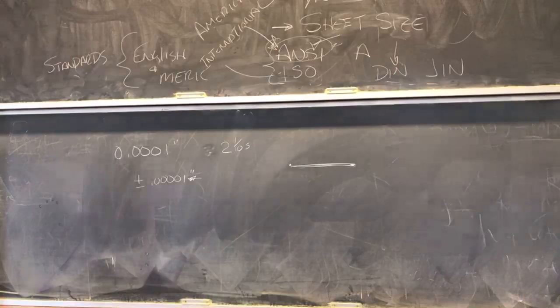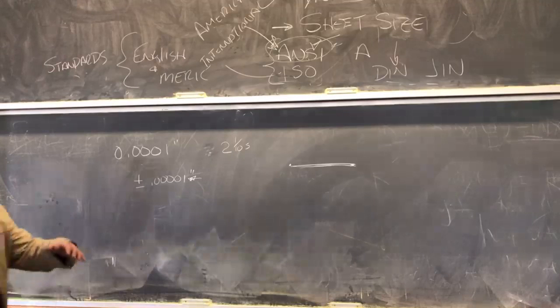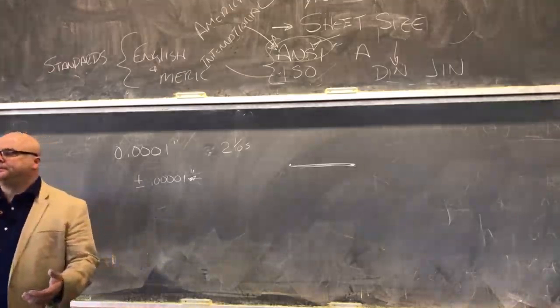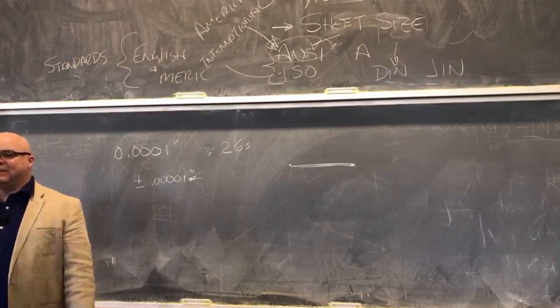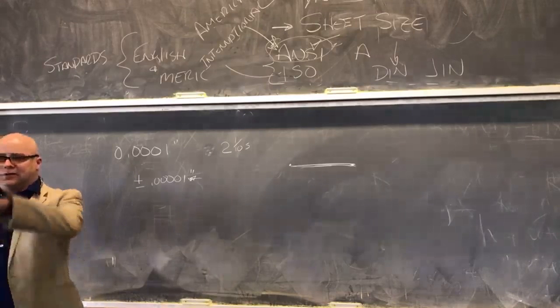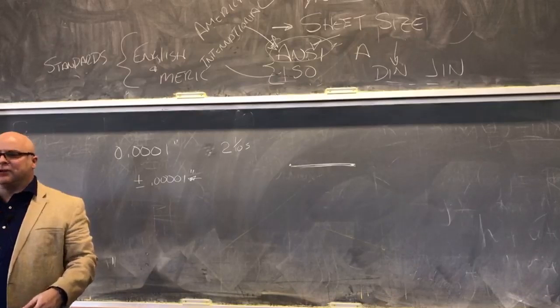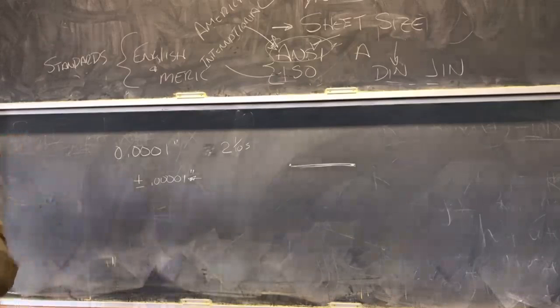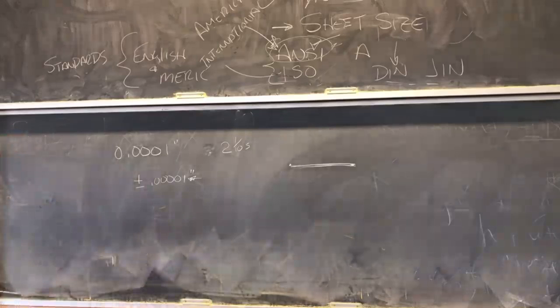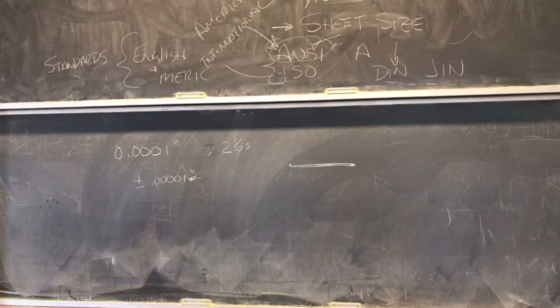If you wanted to reliably make it, now, which machine do you think is cheaper? In general, the one that has the lower repeatability, and by lower I mean not as good repeatability, right? So the one that has the lower repeatability is going to be cheaper, which means, what does that do to the cost of your part?